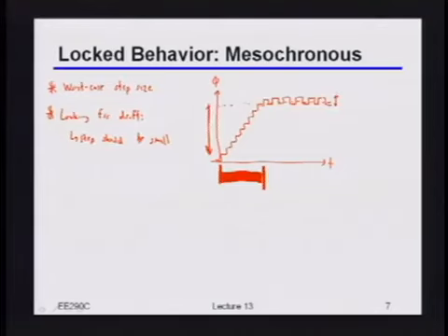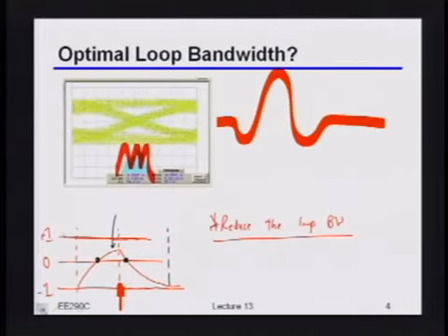And remember we said that, in terms of the CDR, I really don't want to be having anything with very high bandwidth because no matter what I do, I can't really get things right in terms of the data jitter. So my best bet is to just try and filter it out as much as I can, at least the things that are caused by SI, and then only track the really slowly varying components where everything has been statically shifted, right?